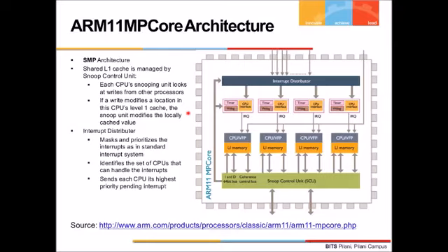This snooping unit looks at writes from processors, and it will try to synchronize all the processors, because there is a possibility that processors will be writing to the memory simultaneously, right? So there should be some unit that synchronizes the writes and updates their own instruction and data caches, right? So the Snoop control unit exists to reflect the latest status of the memory for every processor.